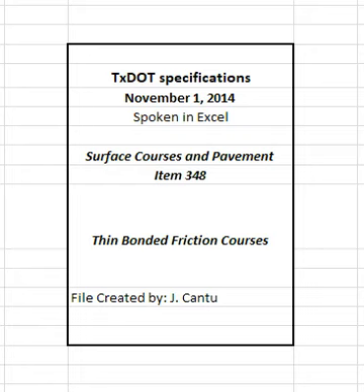Aggregates from sources listed in the department's Bituminous Rated Source Quality Catalog, BRSQC, are pre-approved for use. Use only the rated values for hot mix listed in the BRSQC. Rated values for surface treatment, ST, do not apply to coarse aggregate sources used in hot mix asphalt. For sources not listed on the department's BRSQC, build an individual stockpile for each material.